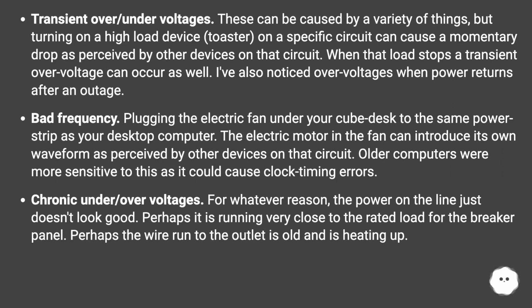Chronic overvoltages. For whatever reason, the power on the line just doesn't look good. Perhaps it is running very close to the rated load for the breaker panel. Perhaps the wire run to the outlet is old and is heating up.